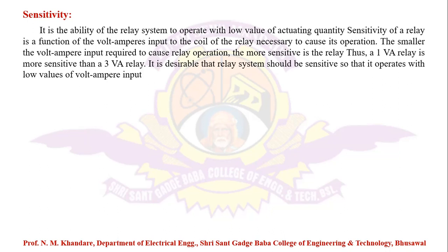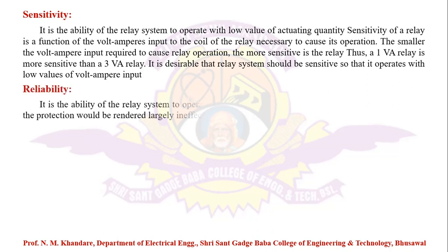The sensitivity of a relay is a function of the volt ampere input to the coil necessary to cause its operation. The smaller the volt ampere input required to cause relay operation, the more sensitive the relay. Thus, a 1 volt ampere relay is more sensitive than a 3 volt ampere relay. It is desired that the system must be sensitive so that it operates with a low value of volt ampere input.